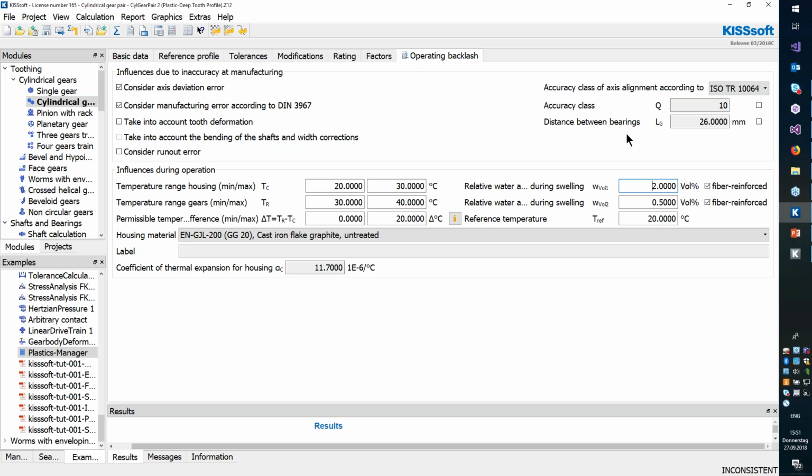So it's always important that the fibers do not break out too soon from the surface itself, either maybe by using long fiber reinforcements or by selecting the appropriate material combination so that the fibers don't do so much damage. It can also happen that they will scratch, for instance, the steel counter gear, but this has to be decided on a case to case basis.